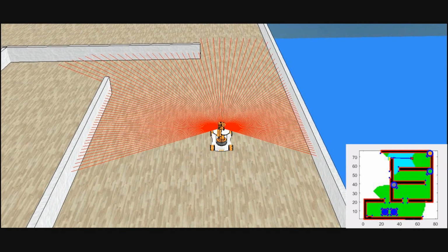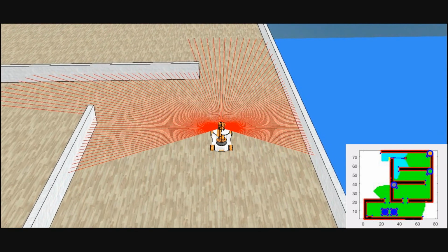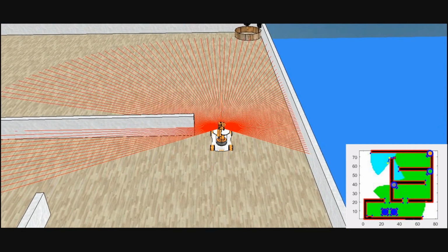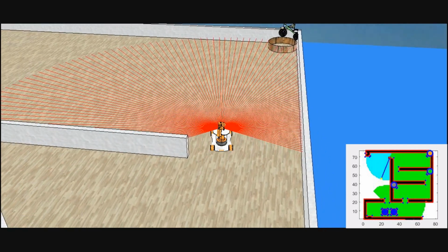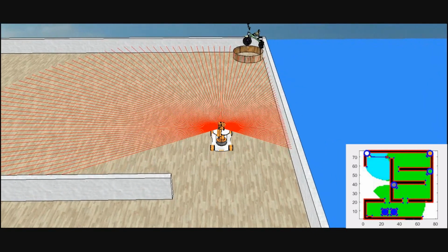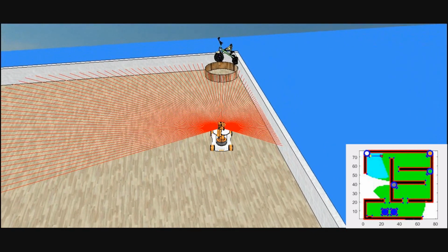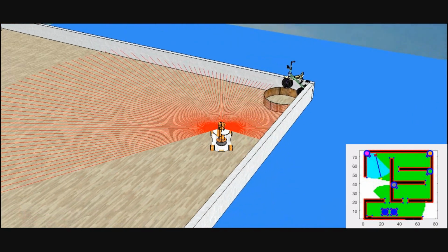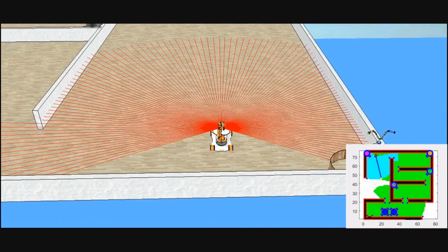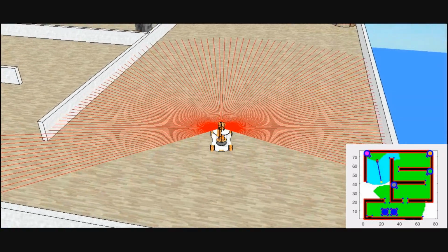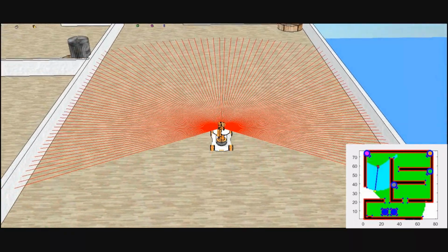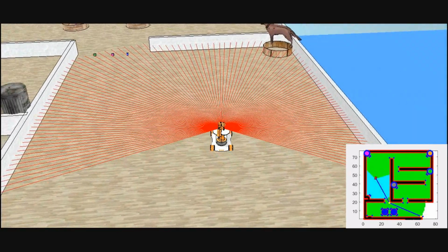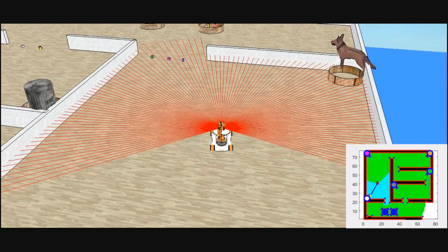The next step is their identification by classifying the 3D markers assigned to each basket, or in the case of the tables, the tables themselves. To do so, we take pictures in front of those objects and feed them to a classifier provided by Matlab that uses bag of features and a machine learning algorithm. The classifier has been previously trained by using a large amount of pictures taken during a large amount of simulations to ensure that they have been taken from different angles and distances.